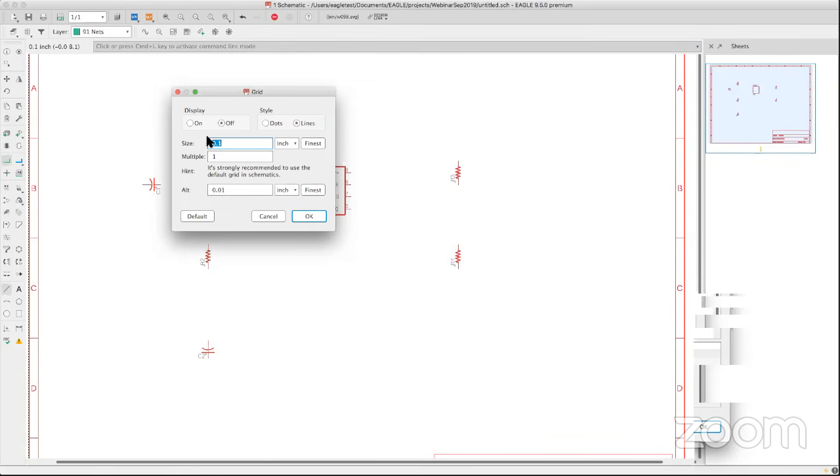But you don't want to get to that point. It's really important. Now, if you have to do any type of graphical aspects to your board, like putting a logo or any type of graphical aspects to the design, then yes, of course, you can change the grid and draw or import whatever you're going to do. But when it comes to placing components and defining connections, I can't stress enough: you need to stay on a 0.1 inch grid.